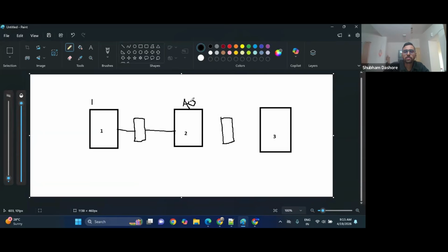Now what happens if some signal is going from the gated domain to the always on domain? Suppose the gated domain has been turned off, but the signal should go from here to here. If this gated domain is turned off, then this signal is zero, and the AON domain always requires that input.